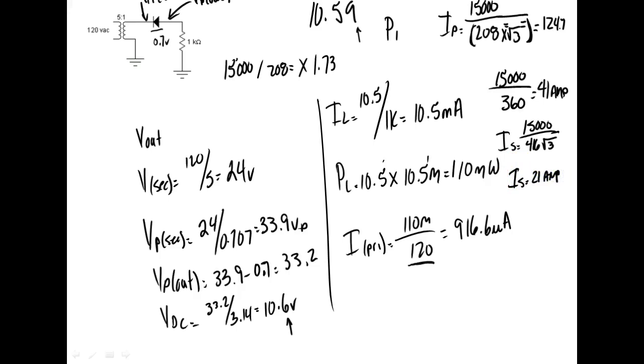And what a lot of people don't understand is power in. Energy out is always going to be less than energy in, right? You understand that? Here we're assuming the transformer doesn't lose any energy, but that's not true, but it's very, very small. So 41 amps, what would I fuse this thing to? Well, I would multiply this by 1.25. If it fell right on the fuse, that's the one I would use. If it wasn't on a fuse size, I would round down, right?